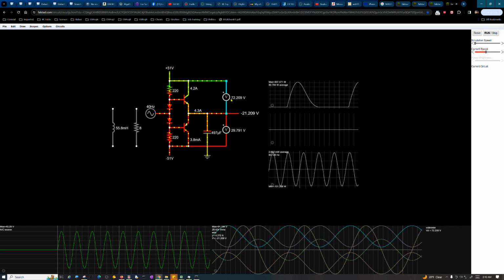That's why it has 72 volts across it. So that's why we're getting huge peak currents, because it's got 72 volts across the transistor, but the voltage across our capacitor is still minus 21 volts. So basically it's in the process of bringing that capacitor from a very low voltage up to ground level, and then ultimately it'll charge it positively.